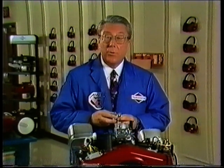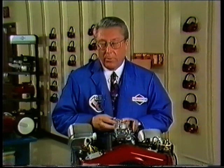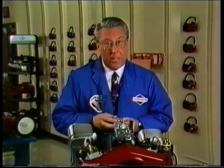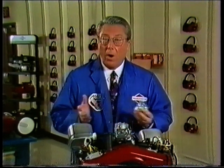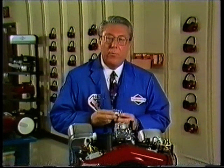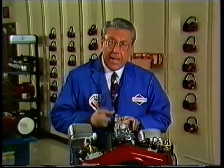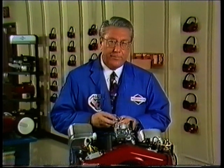There is, however, a small percentage of carburetors whose components might be affected by corrosion, inappropriate fuels, or damage, and may cause leakage. So don't assume that the components are good or overlook any possible cause. Take extra care to prove the integrity of the carburetor and you'll increase your rate of first-time successful repairs.